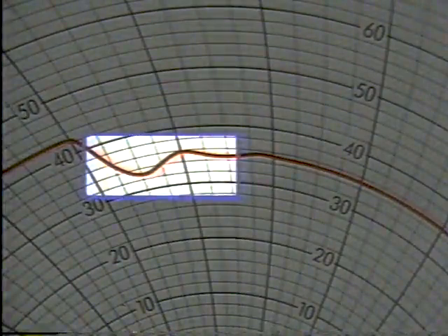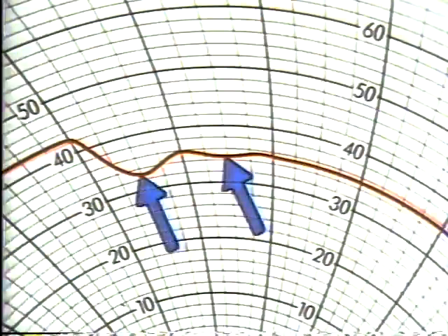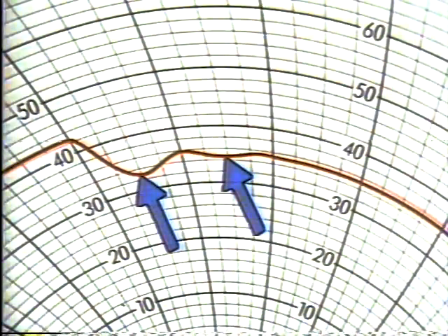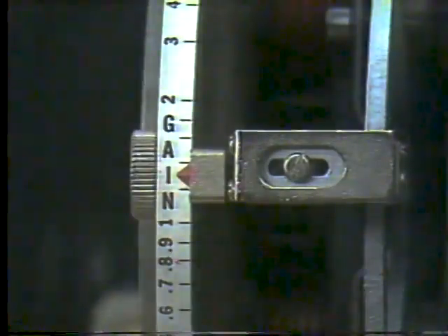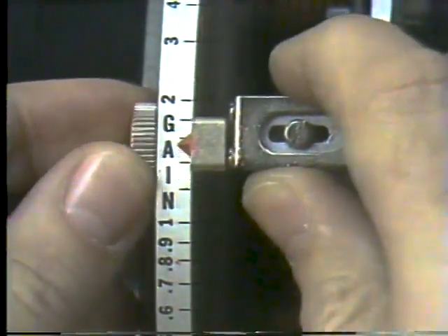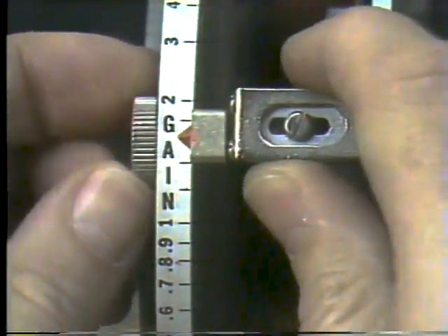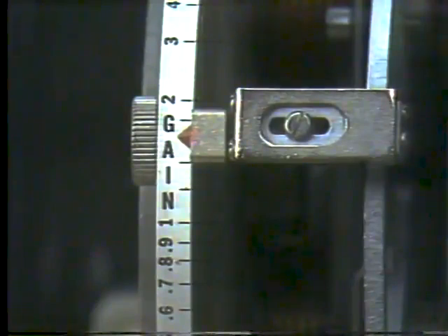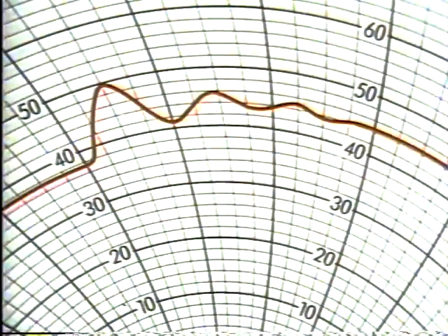There was little cycling, and the decay ratio was still obviously less than 1/4, so he decided the gain was still too low. The third time he adjusted the gain, he set it at 1.6. This meant that it was almost where the engineer had said it should be. He expected it to be either very close or right where it should be. And it was. Here's an illustration of what he saw when he had the gain adjusted correctly.